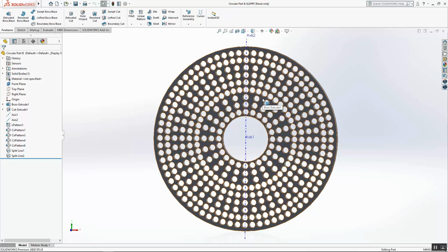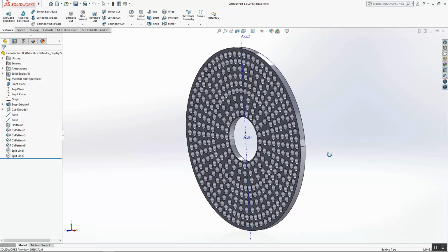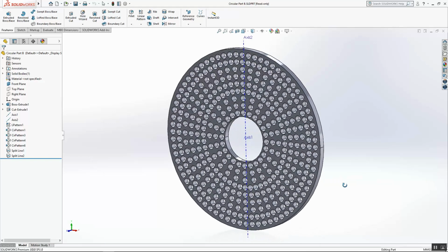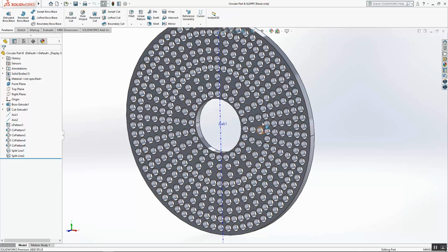So the SIMULIAworks tools basically use a completely different approach to handling contact. And we'll talk about that in both examples, that there are some really unique things that the SIMULIAworks tools can offer us. Now, another thing that SIMULIAworks offers us is the ability to create a brick mesh. So we can see this is a fixed thickness, relatively simple geometry to brick mesh. We would just apply a surface mesh and then sweep that surface mesh through the thickness.